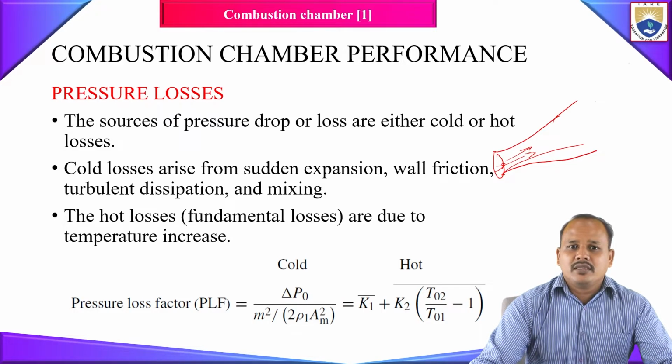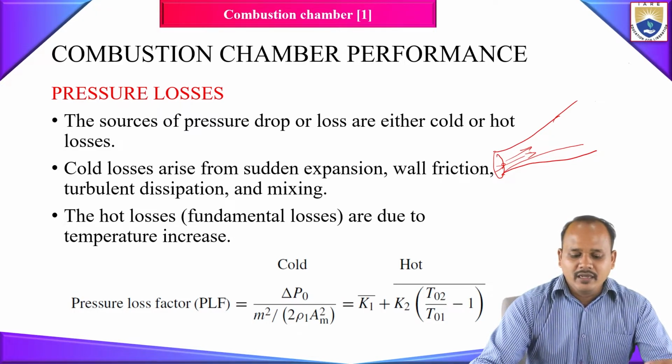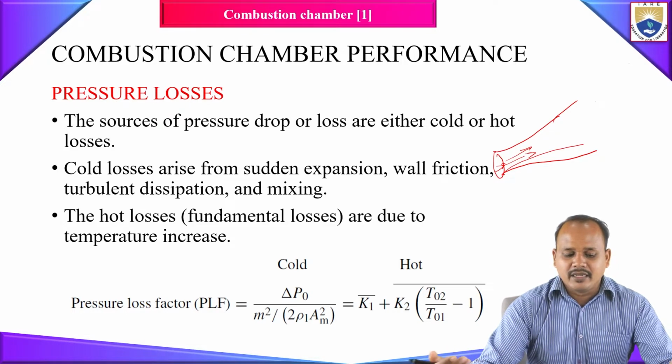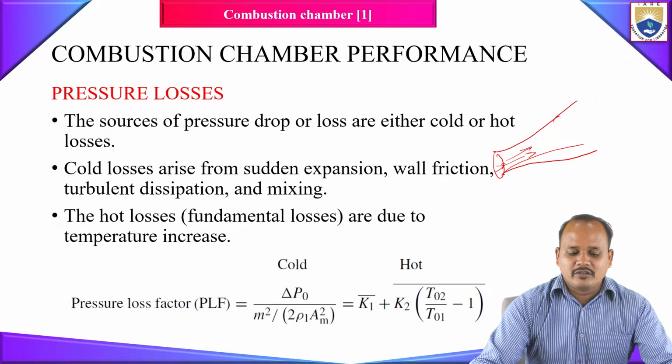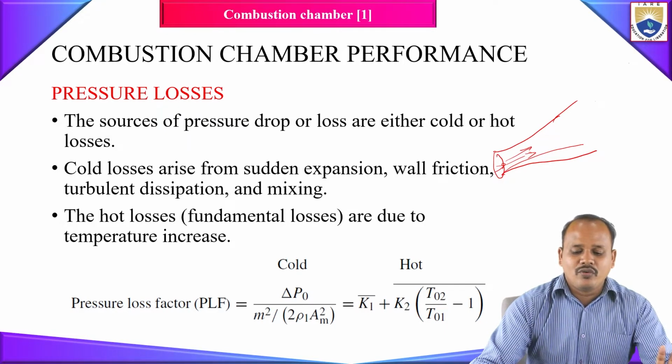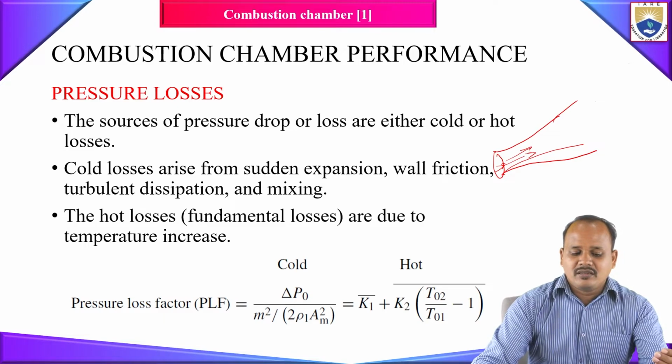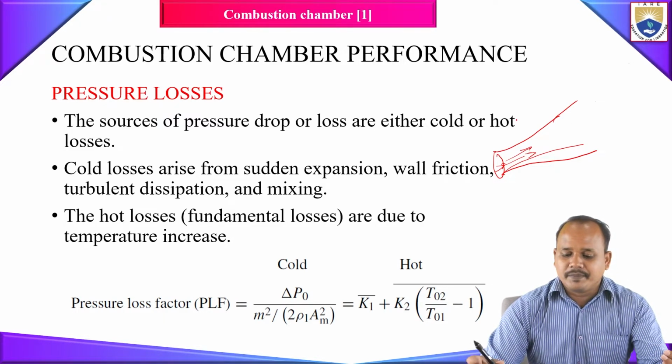the turbulence in your flow field in order to thoroughly mix your fuel and air. So since we are introducing the turbulence, that will obviously lead to some amount of loss. So without doing any combustion, if I simply send this cold flow inside my combustion chamber, how much pressure loss is happening? That's what we call the cold flow loss.